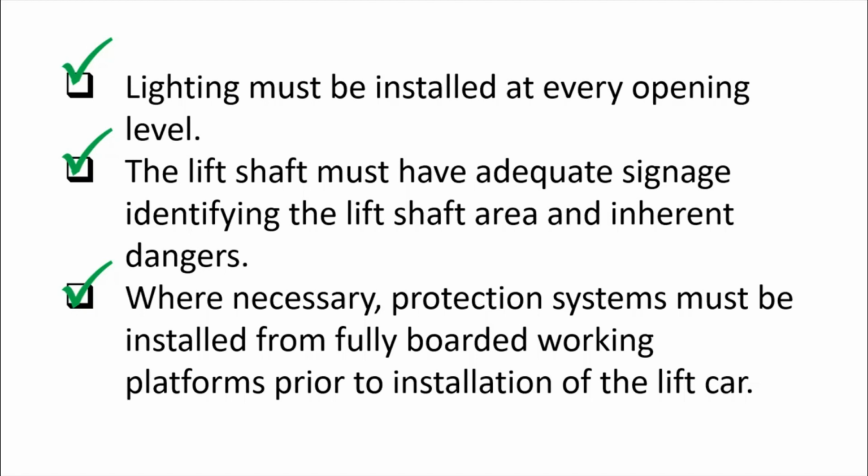So before we install the lift car, we need to install some fully boarded platform under the area that we will install on, so that if anything goes wrong, personnel and other persons are safe inside the lift shaft.